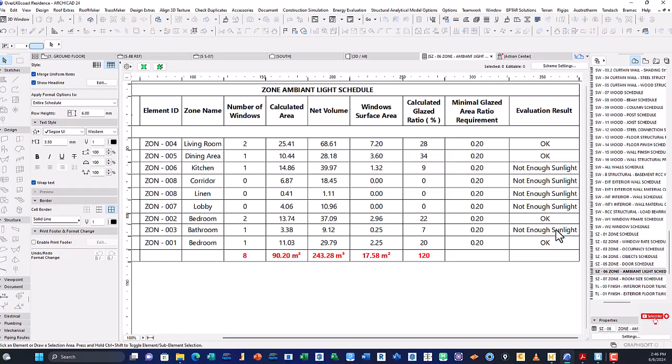Make sure that for the window that appears, that you have applied changes to, you keep in memory or in reference the new sizes that you have entered. And as long as those sizes do not figure on your schedule, there's something wrong. You have to go back to your floor plan and revisit whatever you have done there, because those sizes must appear on your window schedule.